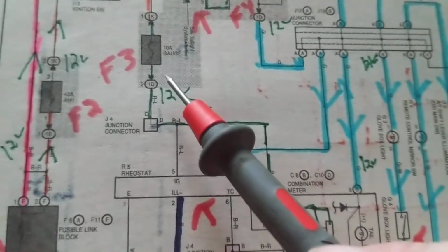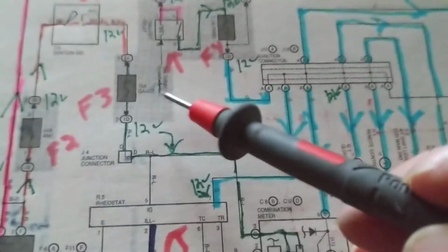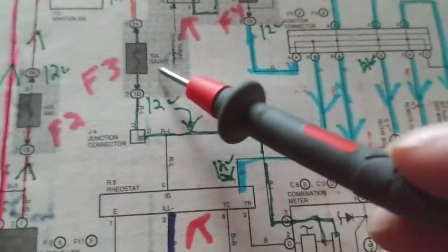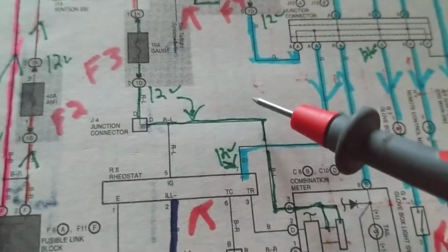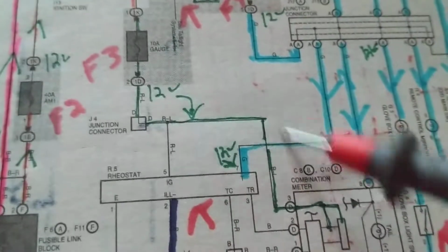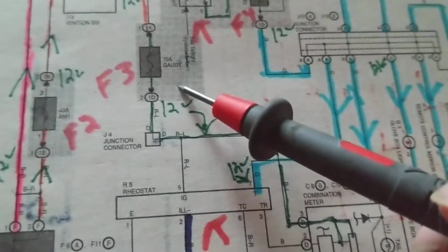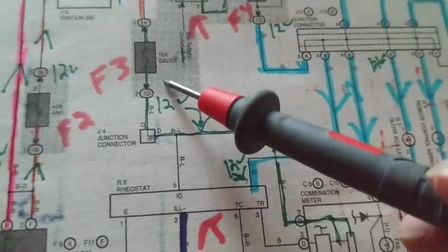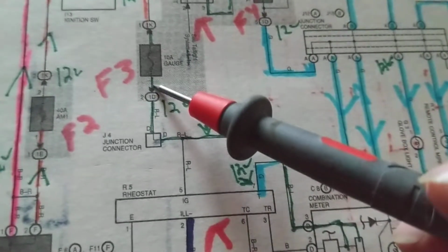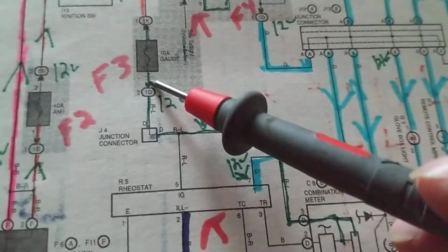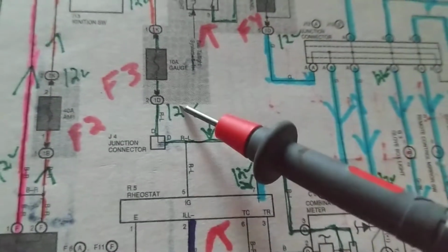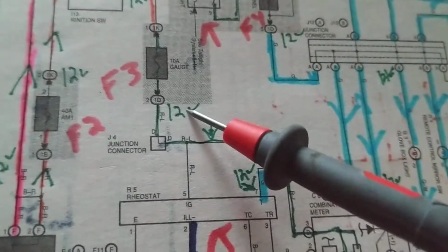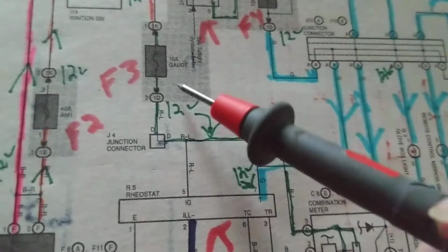None of them are right. If I have 10 amps and I have a 15 amp, guess what? It's not going to protect the circuit, because more amps will be allowed to flow in the circuit. That's the wrong answer. Do I put less? Well, if I have 10 amps and I put a 7 amp fuse, when the circuit does draw 7 amps, it'll blow it every time. What's the answer? Put a circuit breaker if you have it. Right? Put a circuit breaker.